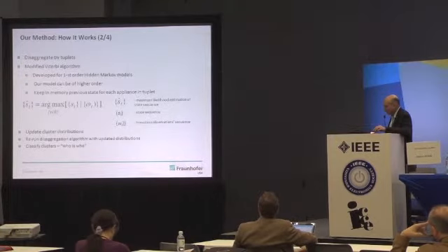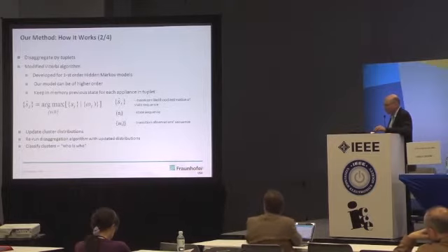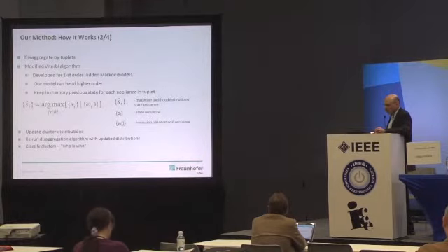We have a system which resembles a first-order Markov chain here. In reality, it is not exactly a first-order Markov model because there could be missed or foreign data, so that the state of the system at a given time corresponding to a power change may depend not only on the previous, but on several previous steps. So the solution for that is a modified Viterbi algorithm.